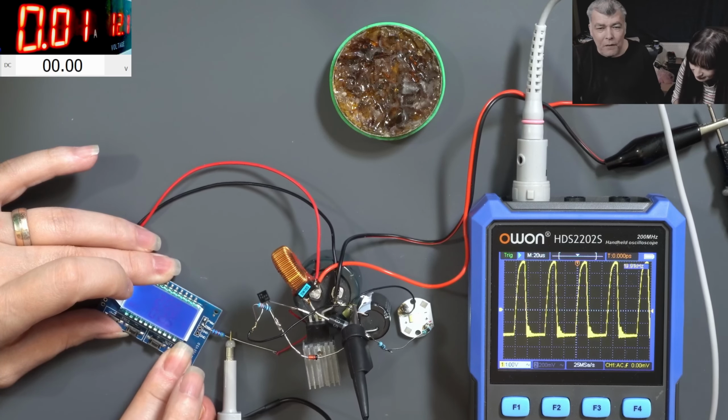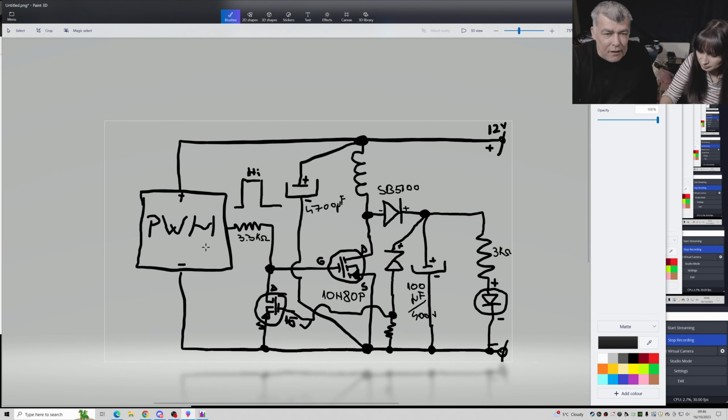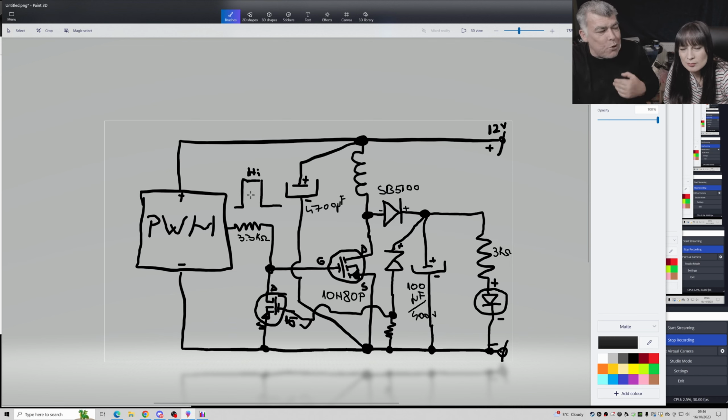28, yeah? So you understand what is happening. Basically, even if you come here, this is delivering a different duty cycle. This transistor is switching to ground whatever is extra. Even if you push more duty cycle, the transistor will switch to ground whatever is extra. That's why it's not changing here. So whenever the voltage goes up, it will cut down the duty cycle, no matter what duty cycle you have here.